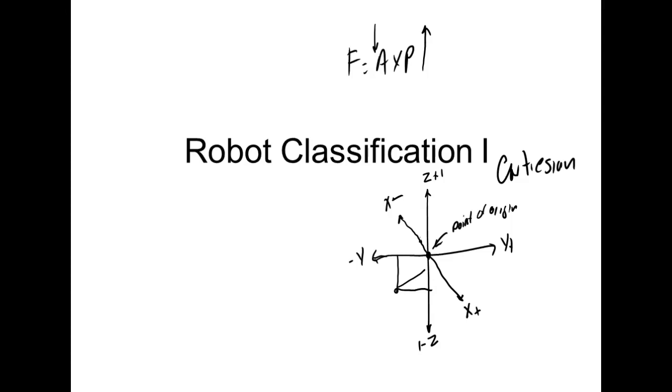We have what we call frames. You can reorient the robot on how it records points. So if I'm always working on a slanted surface and I want to set it up so I come back 15 millimeters from that surface, that makes all the difference in the world. So we can teach frames. We call them user frames. And from then on, the points are stored relative to my application, not the one that the factory considers to be their application. So that's long, and we're going to go over that again before we start on this chapter.